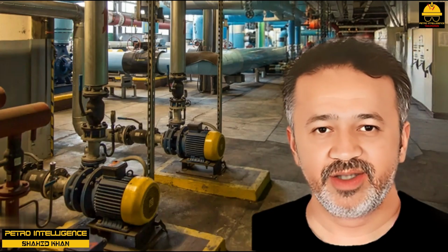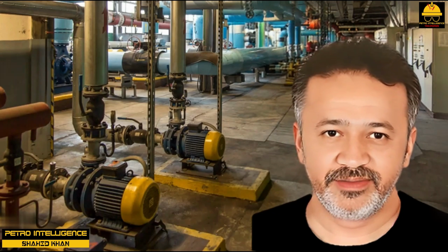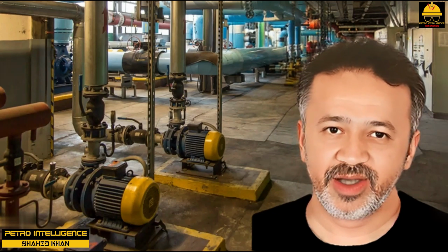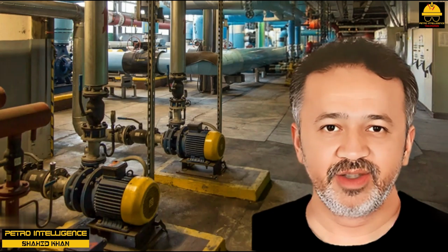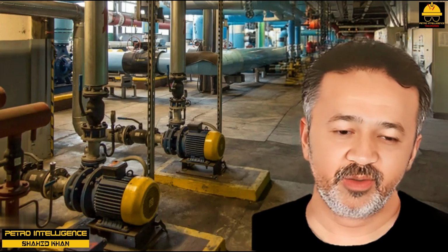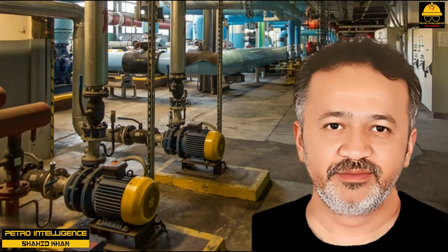There will be a small loss of 3% in motor efficiency by using an oversized motor. As process operators and engineers, we can ignore this effect. It is good engineering practice to purchase new motors for the maximum size impeller that can be installed in a pump.